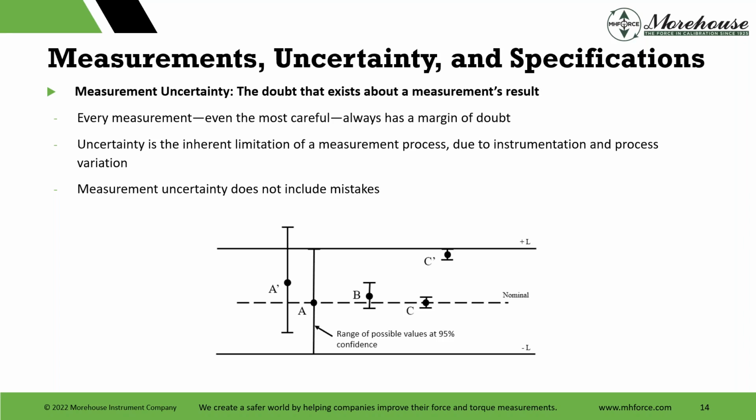We think we know our measurement when we apply our dead weights to 0.002% of applied. We think we know it's that good. There is some doubt. We don't know that if we apply 10,000 pounds, it's exactly 10,000 pounds, but we think we've done our uncertainties well enough that we know it within plus or minus 0.002% of applied, or 20 parts per million, and then we add this unit under test and what it contributes. So anything has, even back to the SI, some doubt, some unknown.